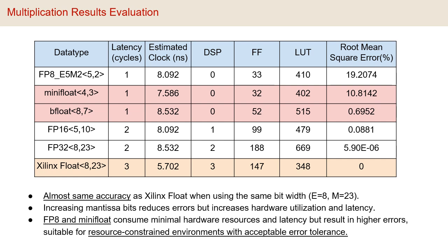Floating point 8 and mini-float, which are generated by our templatized floating point unit, consume minimal hardware resources and latency, but result in higher errors, making them suitable for resource-constrained environments with acceptable error tolerance.